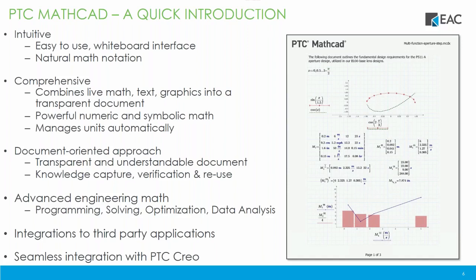And perhaps something that's very important to mention is that the engine is units intelligent. So Mathcad knows what units are, it tracks units, it propagates units throughout calculations, it converts units, it takes care of all of the units handling and units management for us, so that as engineers, we don't have to worry about converting feet to inches. We can focus on the actual engineering problem.